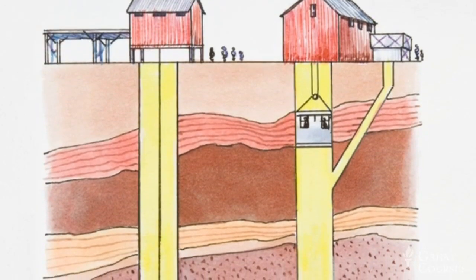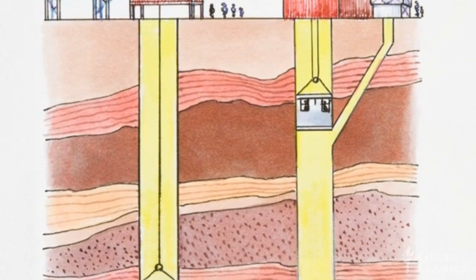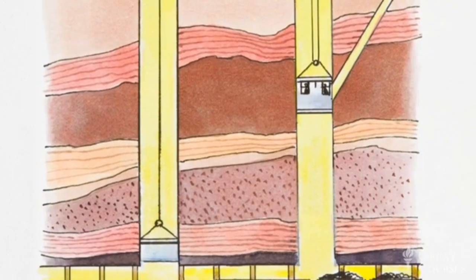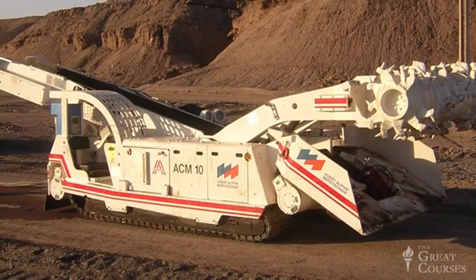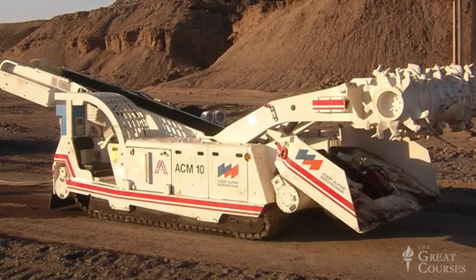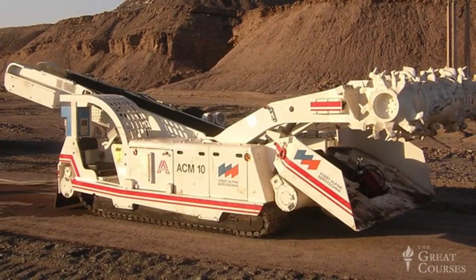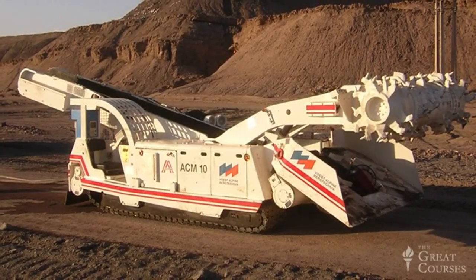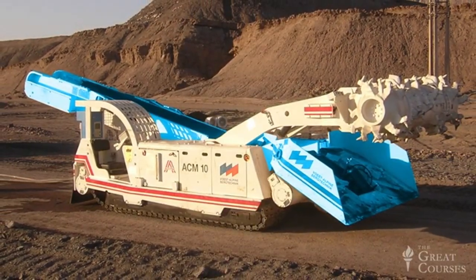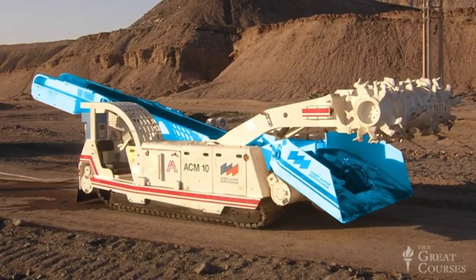In the typical underground mine, a shaft is driven from the surface into the coal seam, where a maze of tunnels extends progressively farther outward as mining operations progress. Back in the day, these tunnels were excavated by individual miners who set off explosive charges at the head of each tunnel and then mucked out the resulting debris with shovels, wheelbarrows, and carts. Today, both digging and debris removal are performed by this continuous mining machine, a low crawler-mounted vehicle that incorporates a fearsome-looking cutter head mounted on an articulating arm, and a scoop and conveyor system that gathers in the excavated coal and transports it away from the excavation.